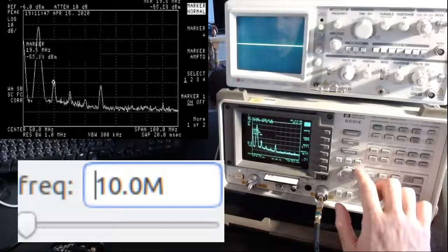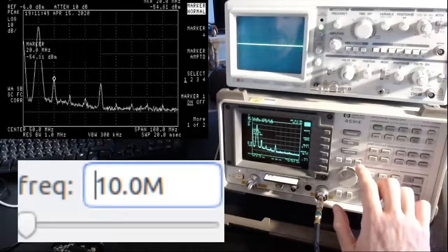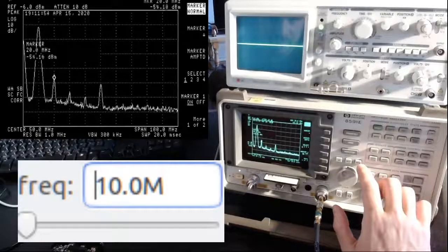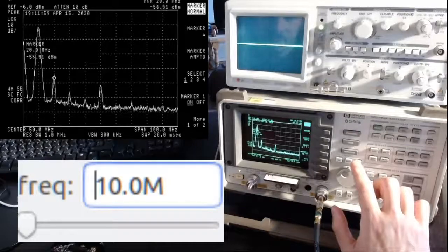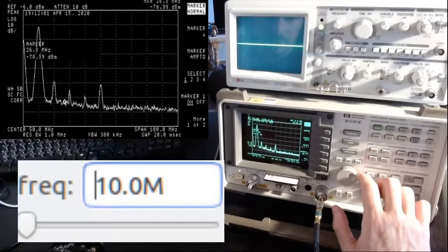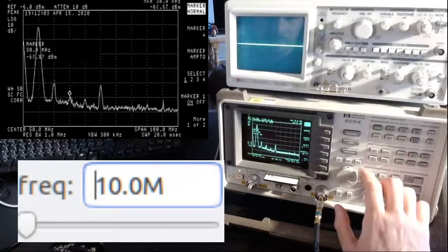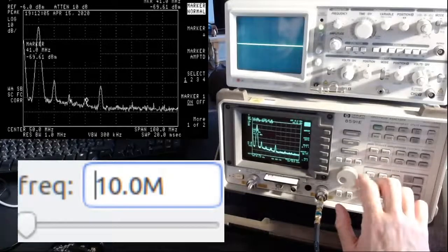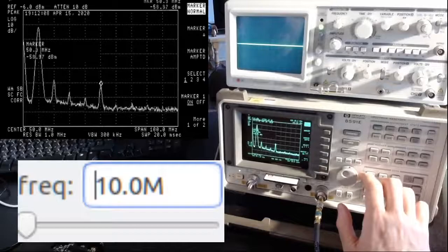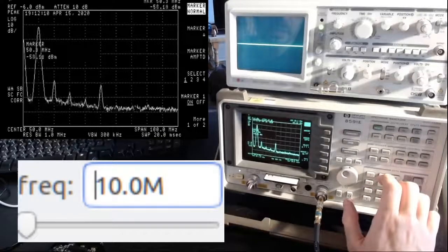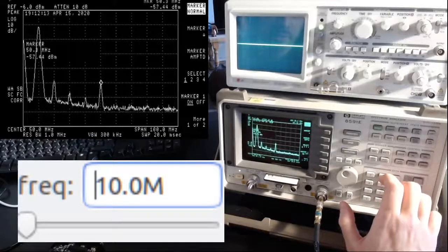And there are some harmonics. Namely, there is this first harmonic at 20 megahertz. It's about 3 and something divisions down, so minus 30 dB, which is 35 even, which is, I mean, okay. There is the third harmonic, the fourth harmonic, the fifth harmonic. So I think we can say 35 dB down in terms of additional unwanted harmonics.